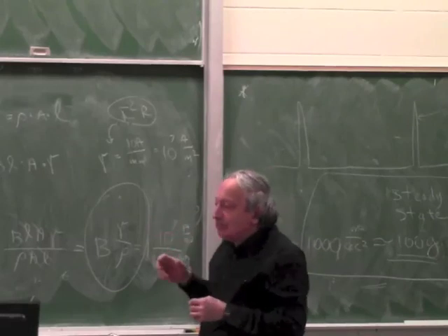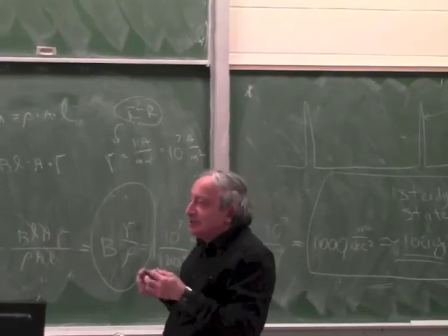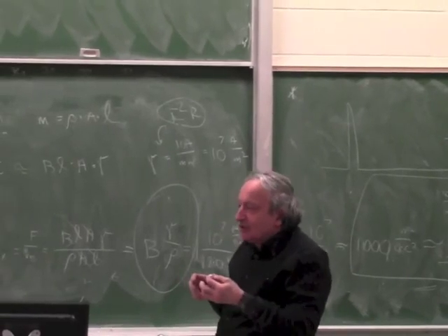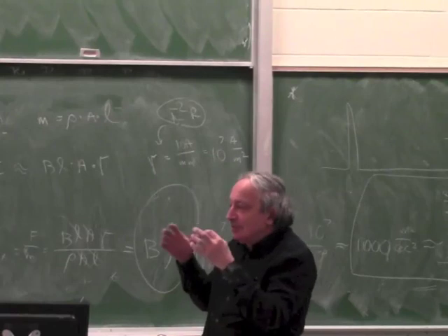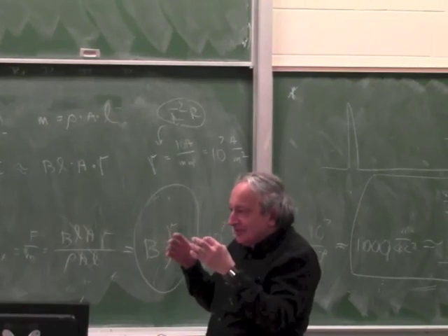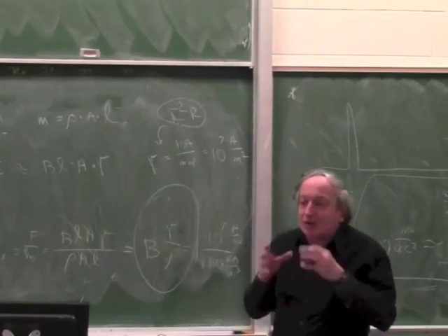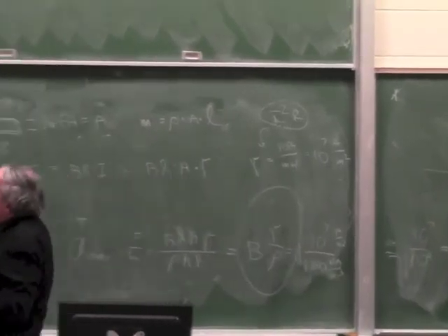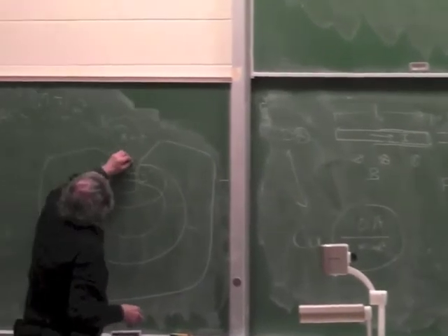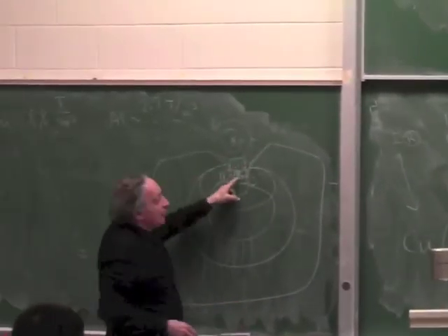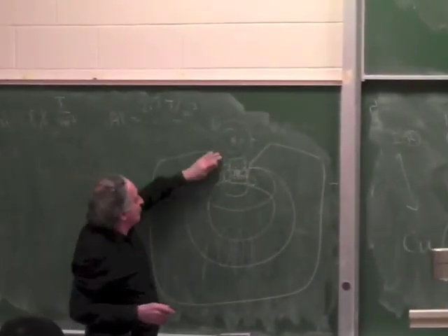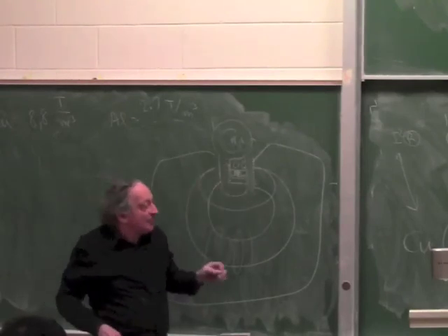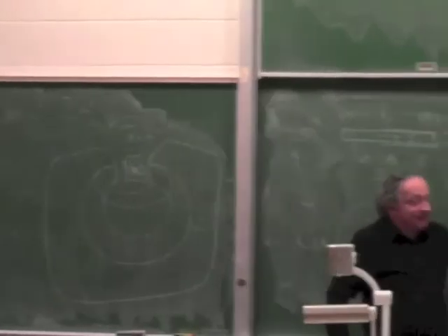If the wire is aluminum, it doesn't conduct as well as copper, so it gets hot. In order to keep the heat down, the aluminum wire has to be a bit bigger. That means the coil is a bit bigger, and the problem it causes is, if you want to fit the coil inside the magnet and you make the coil of aluminum, it's a bit bigger, you have to make the gap a bit bigger. And if you make the gap a bit bigger, B goes down a little bit.